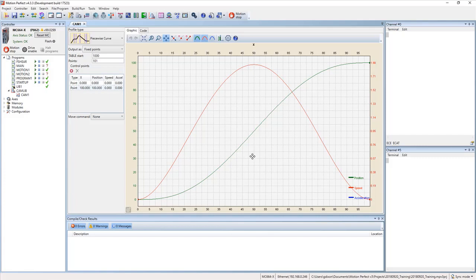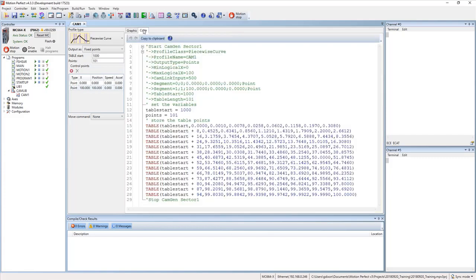It's based on the encoder resolution and the distance you want to move. There's not a lot of point in having that number unless you've got a move that takes 512,000 milliseconds. So 512 seconds to complete the move, because you'll only get 1 point per millisecond anyway. Yeah. And that's the total memory space for cams. That is the total. Multiple cams, then you would have to divide it up.